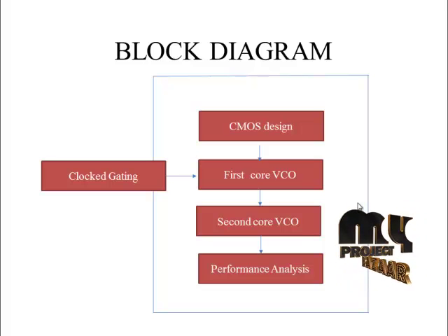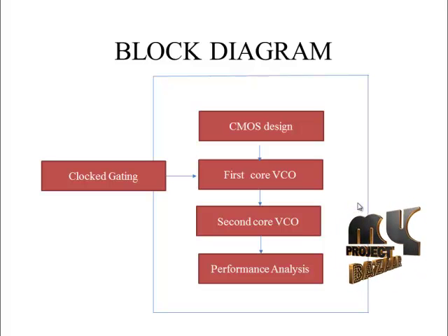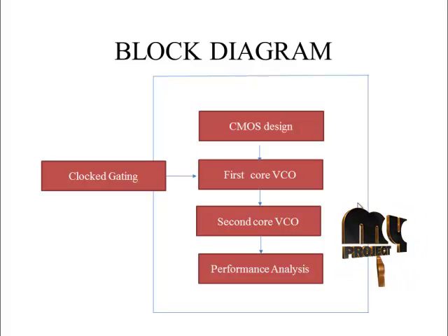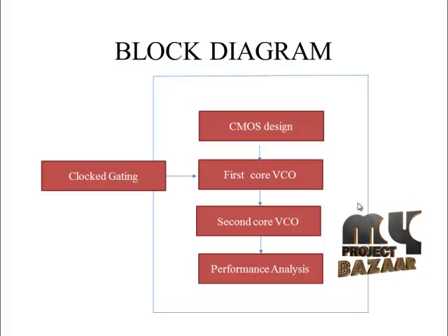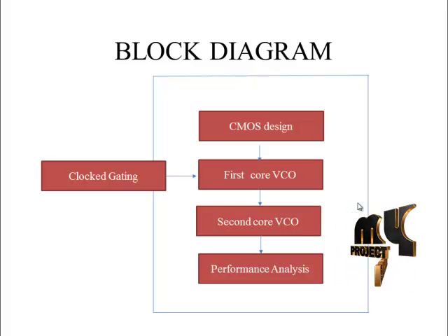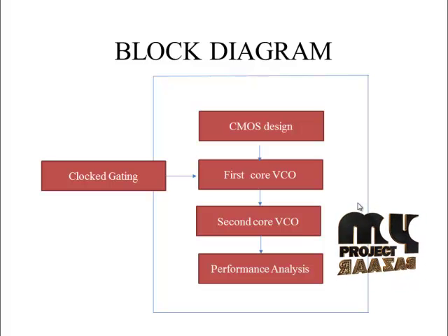According to our modification, the second core VCO modifies the overall circuit, and for the overall circuit we are applying the gating which is clocked, and finally from the overall design we obtain the simulated result through the Tanner EDA at the waveform editor, and finally from the obtained waveform we see and verify the performance report.